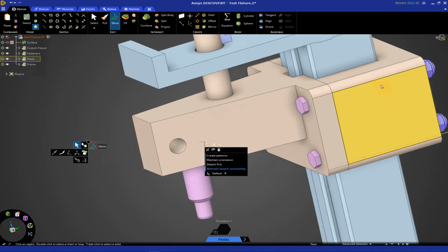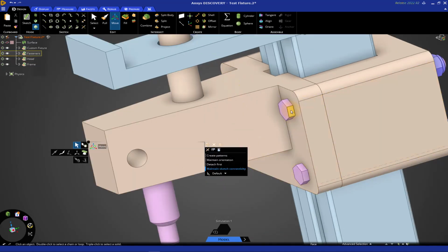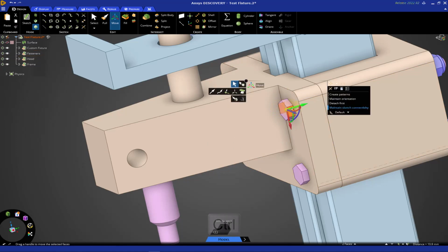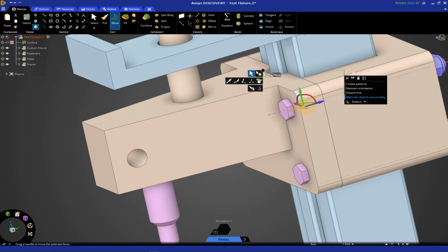We might want to go into a cross section through this bolt, and I could select these parallel faces here by holding Control and scrolling through the model, or it's also common to select the axis through the pin or the hole. So if I hold Control and scroll my wheel, it will toggle to the hidden faces, and if I hover over that center and I keep spinning, now it's selecting the axis and I can select it from there. Now we want to enter section mode, and that can be done from the Design tab in the upper left or X for keyboard shortcut.